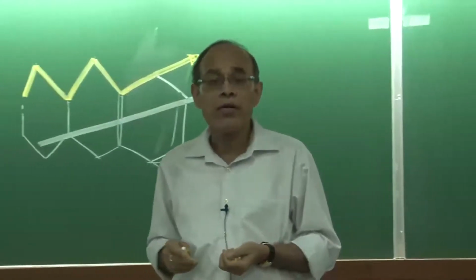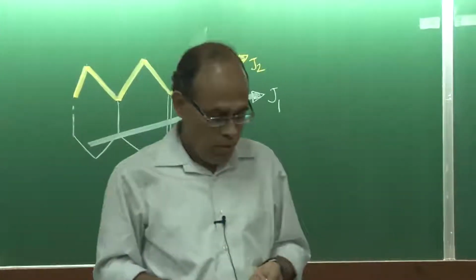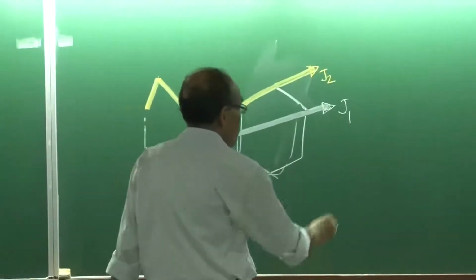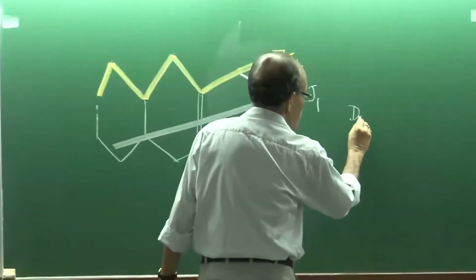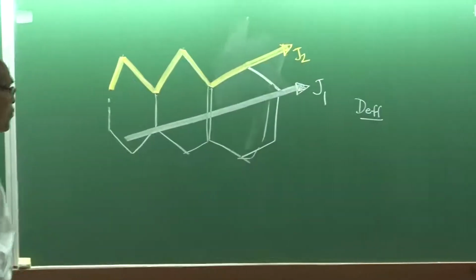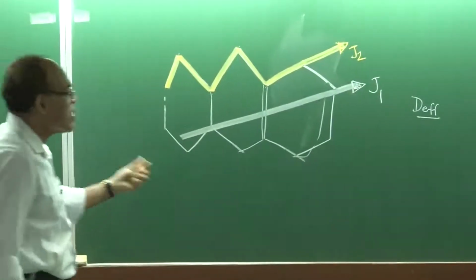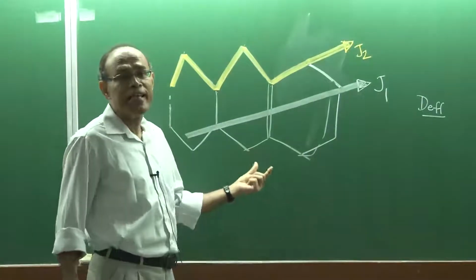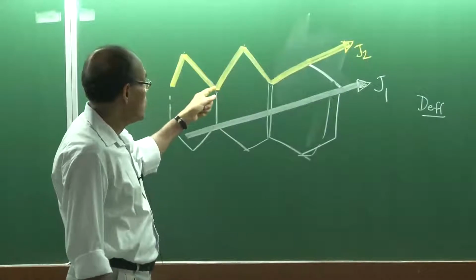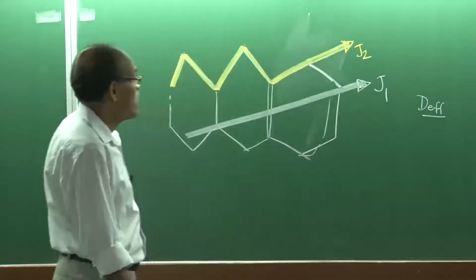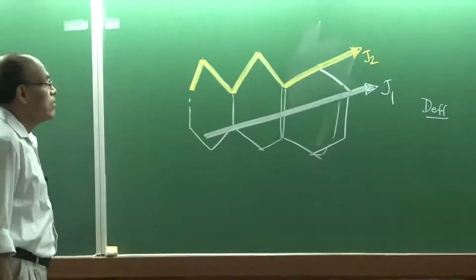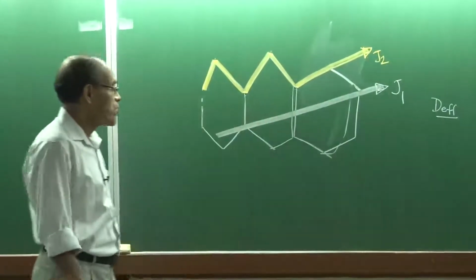So we continue with our discussion on diffusion through the grain and grain boundary, and in that context, if you remember in the last lecture, I introduced a parameter, the effective diffusion coefficient, and this is necessary even though for a single material, as I have indicated, the diffusivity through the grain boundaries could be substantially larger than the diffusion through the lattice. And so these are grains of a polycrystalline material.